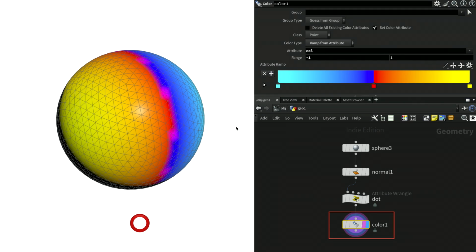So the yellowish color determines the value which is more than 0, and the bluish color determines the dot product value is less than 0. So negative value and positive value. So what we can see is that if you have a big island of a positive value, then that ensures that you are able to use it as a mold. You can pull out the mold shape.